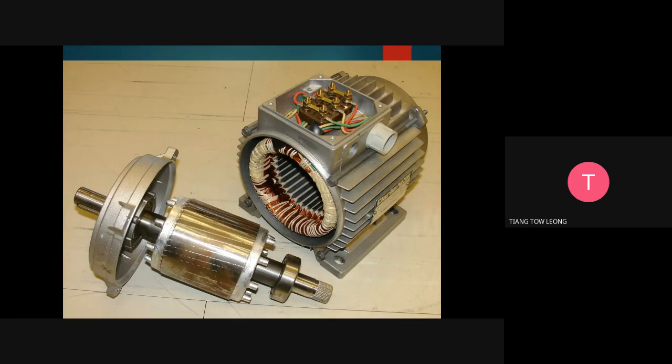This one is an induction machine. So this is a stator. Usually we first need to see the rotor. Okay, shaft. Then bearing. Nameplate. This is the radiator, we call it sink. Then the winding. This is a laminator, I think paper laminator. So we can see this is a squirrel cage.